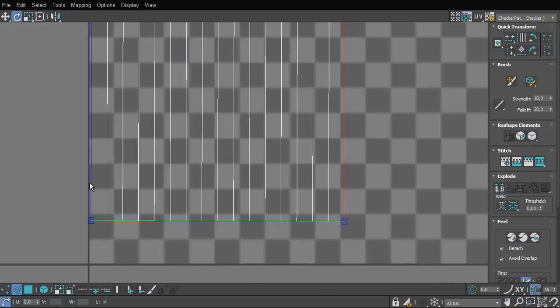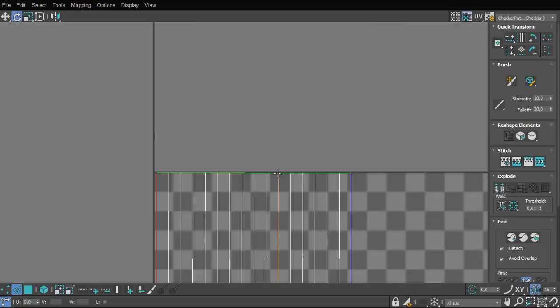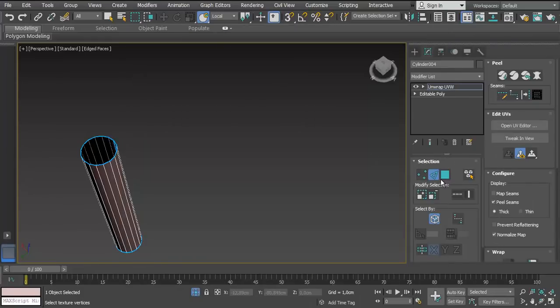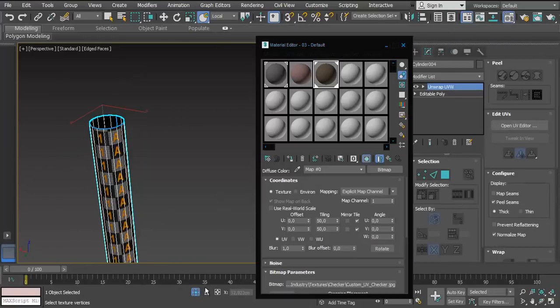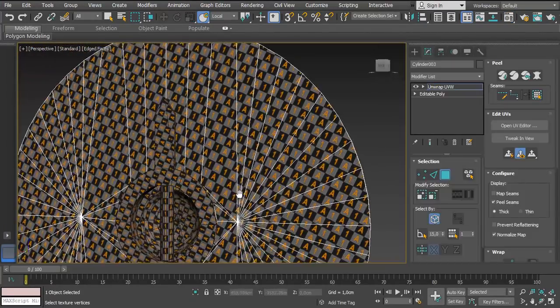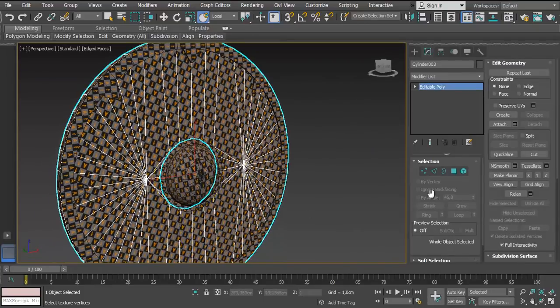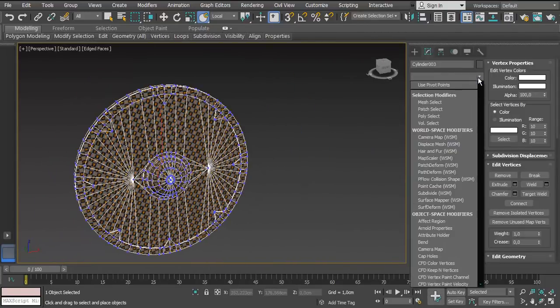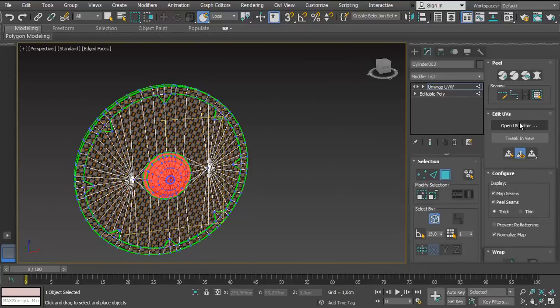Okay, also another thing we need to keep, this is something I talked about a lot, which is to keep the outer edges straight when it comes to the UV islands. You need to make sure to keep all the outer edges straight in order to avoid any kind of scaling effect or something that is gonna look distorted when it comes to baking the maps in Substance Painter.